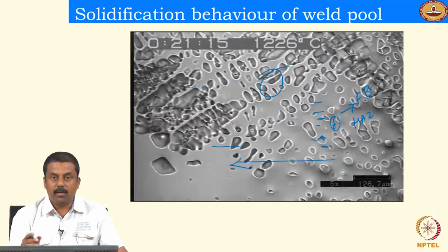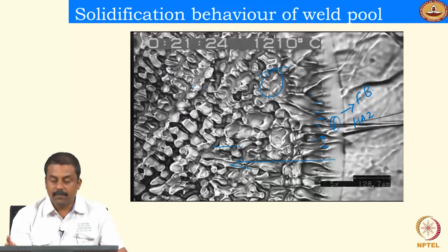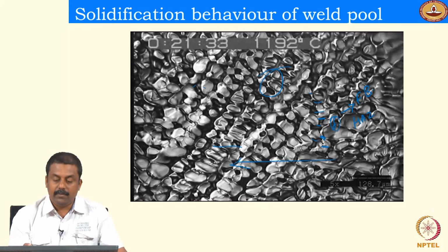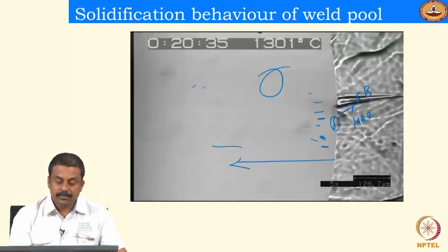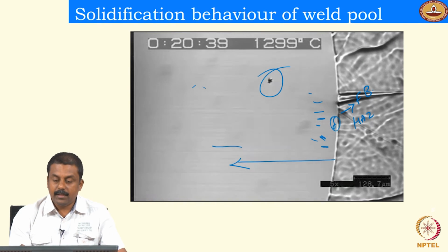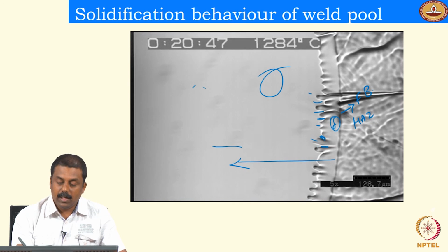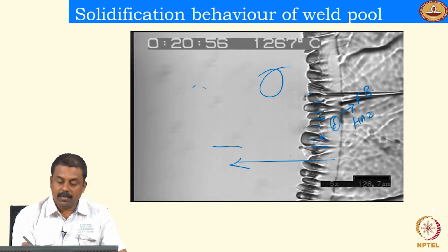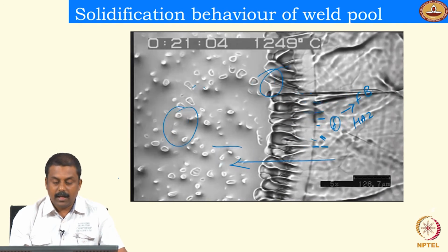And because the carbon concentration of the liquid is always higher than the solidifying products, the carbon would tend to segregate towards the unsolidified liquid, thereby enriching the liquid during solidification. So if you look at this solidification mechanism, you will have a partitioning of carbon to the unsolidified regions at the interdendritic boundaries, as well as the liquid solidifying at last.